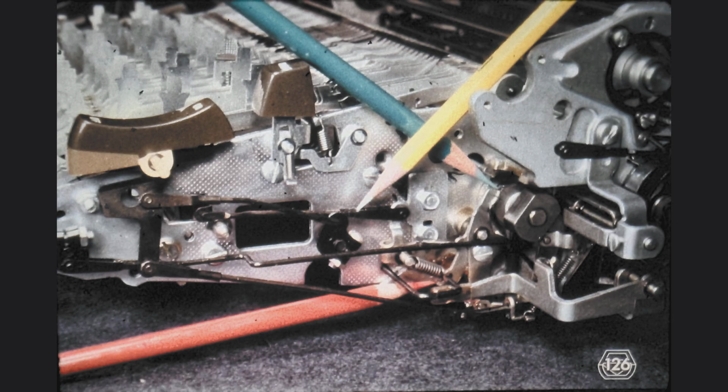Notice also that the low-velocity mechanism restoring cam has 2 scribe marks on it. At rest, the cam should be positioned so that the first scribe mark on the cam, below the green pencil, is aligned with the mark on the cam follower. You can easily check your adjustment of the length of the link.